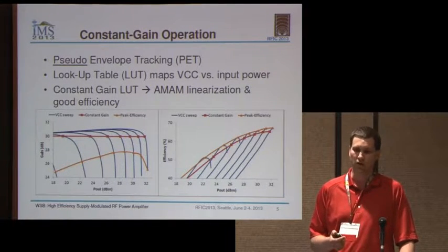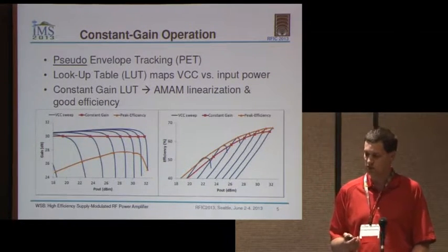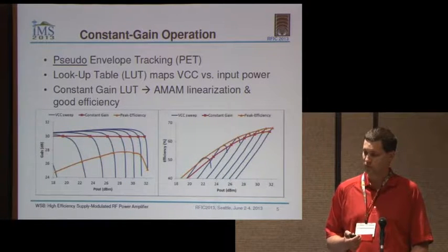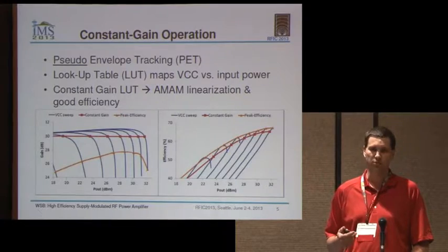And our goal in the handset space is to provide envelope tracking without requiring digital pre-distortion of the RF input signal into the PA. In a system that could provide RF pre-distortion for the input signal, you could correct for that AM to AM distortion. But in our application, we're trying to avoid that.